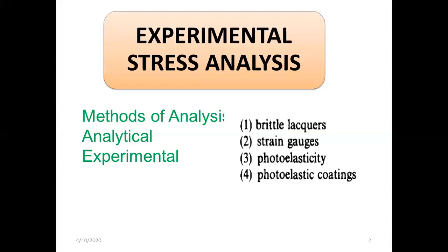So if the engineer has no other way of assessing stresses except by recourse to the nearest standard shape and hence analytical solution available, he builds in greater strength than he judges to be necessary. Thus, that is by incorporating a high factor of safety in the hope of ensuring that the component will not fail in practice, which means unnecessary weight, size, and cost, not only in the component itself, but also in the other members of the structure which are associated with it.